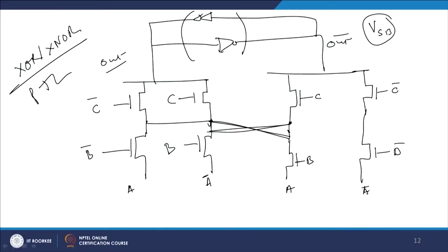I will give you an example. Let us suppose this is A, and this transistor is there. Let us suppose this shows a 1 here, A equals 1, the voltage here rises, VSB becomes larger, and there is a change in the threshold voltage. Let us suppose VT1 was initially 0.5 volts, and now it has become 0.3 volts, VT2 after the change. So, you require a lesser amount of voltage to do it, fine, or the reverse.